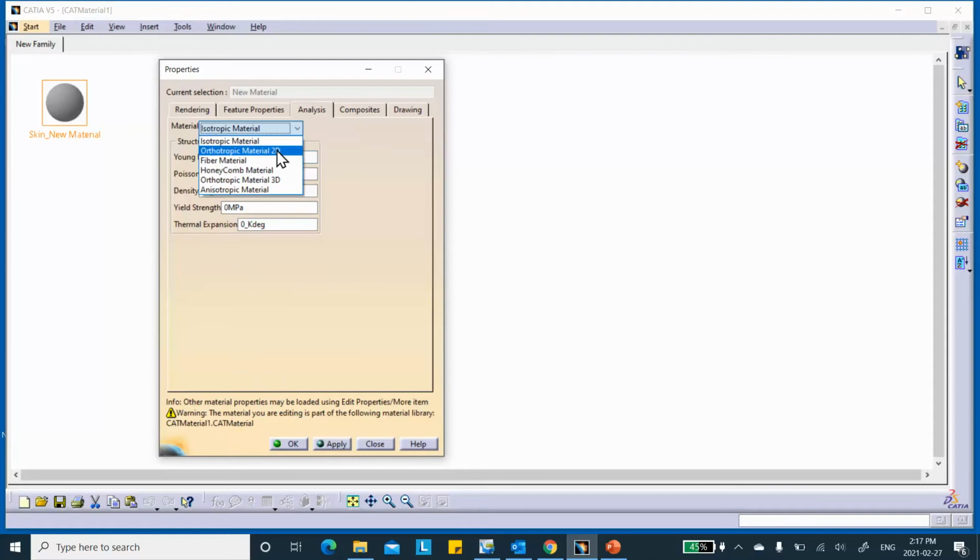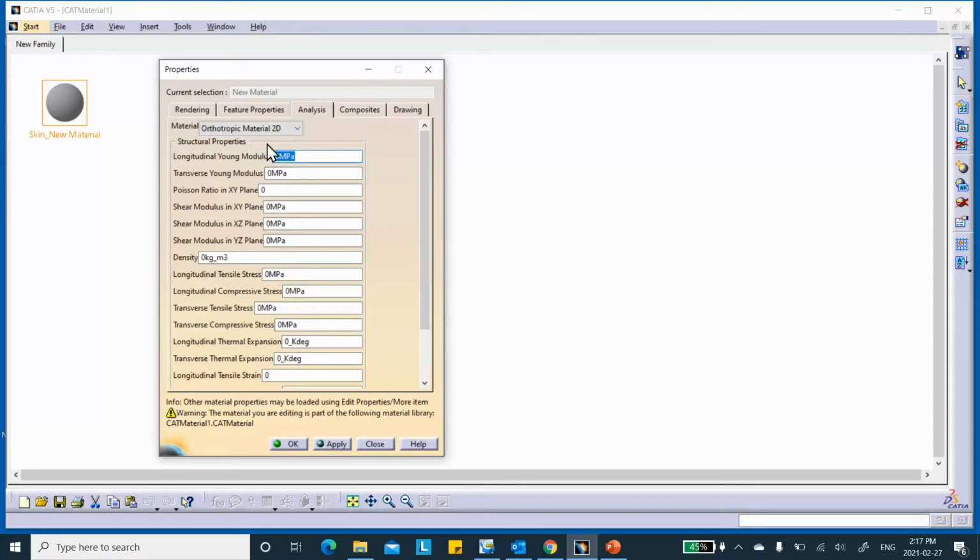We're going to use 2D orthotropic, and these are the numbers that I was talking about. So this one is 68947 MPa. This is the Young's modulus, longitudinal modulus for the lamina, and then this one is 27579. The Poisson ratio, we are told, is 0.3. The shear modulus in the 1-2 plane, or the XY plane, the plane of the lamina, is 12928 megapascal.